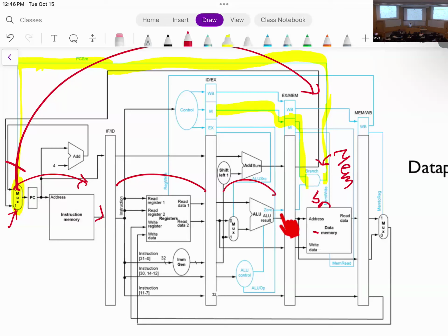The question is about this AND gate happening in parallel. Yes, remember, this is still hardware, so everything happens in parallel for each stage. For example, this signal, all of these things, like your immediate generation, happens in parallel with your register file. So within one stage, everything happens in parallel. Between different stages, there is the clock signal.